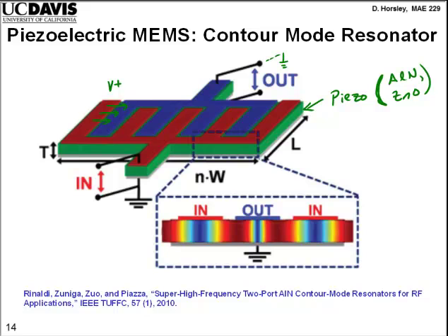They look like this. This is the E field. From the red to the blue, we have opposite electric field lines. This is inside the piezo material. Here's a cross-section view down below. If we have a plus electrode, then we have E going this way, and then E going this way here.